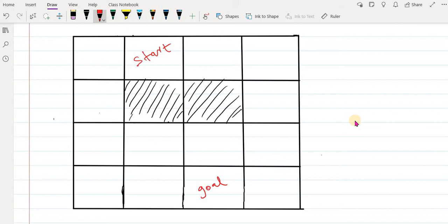Of course, these are some values of the angles of your robotic arm, for example θ1, θ2, or in case of your mobile robot it will be some x, y locations in your configuration space. So we want a shortest path from the start location to the goal location, avoiding these obstacles in the path.